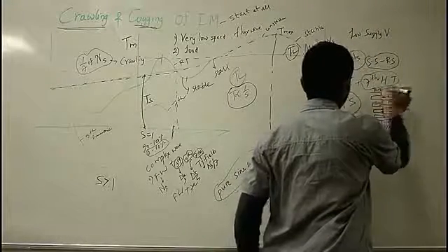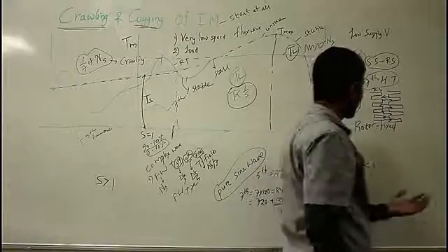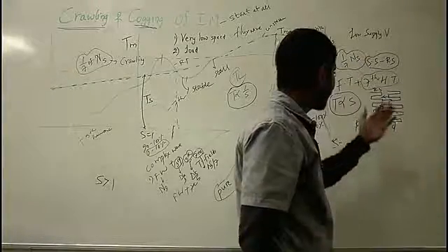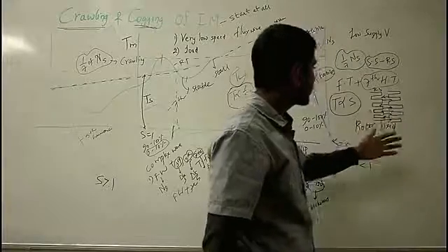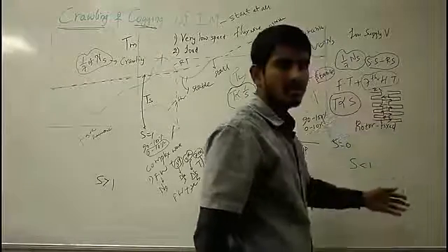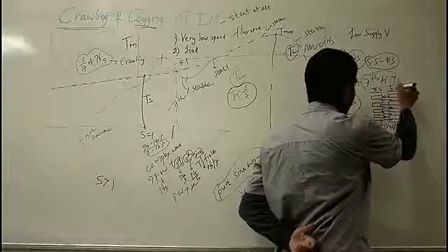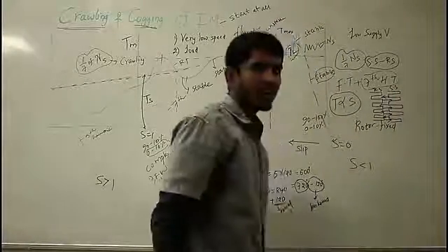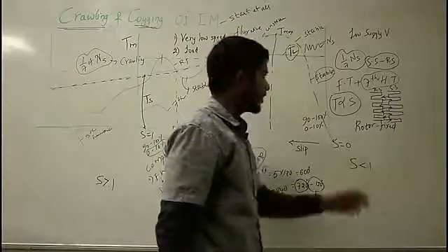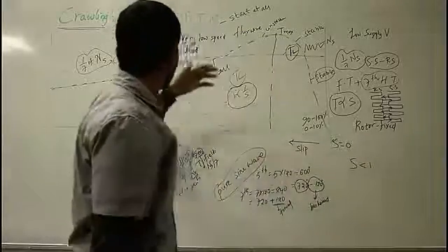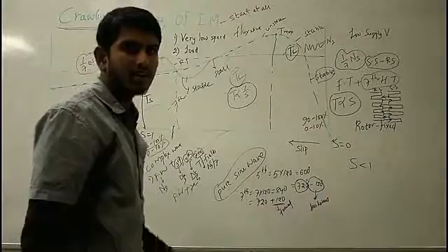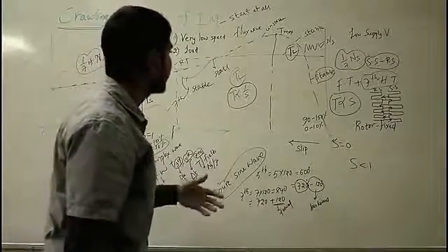So when the slots of the rotor are equal in number with the slots of the stator, they align themselves in such a way that they both face each other, and the reluctance of the magnetic path is minimum, and at this point the rotor remains fixed and the motor refuses to start. So this effect is known as cogging of your induction motor. You can say the magnetic teeth locking of your induction motor.